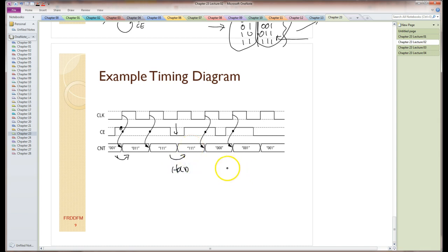Once again, this is what the outside world sees. It doesn't see the actual state variables or the output of the underlying register in this problem. That's very typical. For all the previous problems, the output of our circuit was the output of the state registers. For this problem, it was not. We had to drop an output decoder in between to essentially massage the output into something that we wanted.